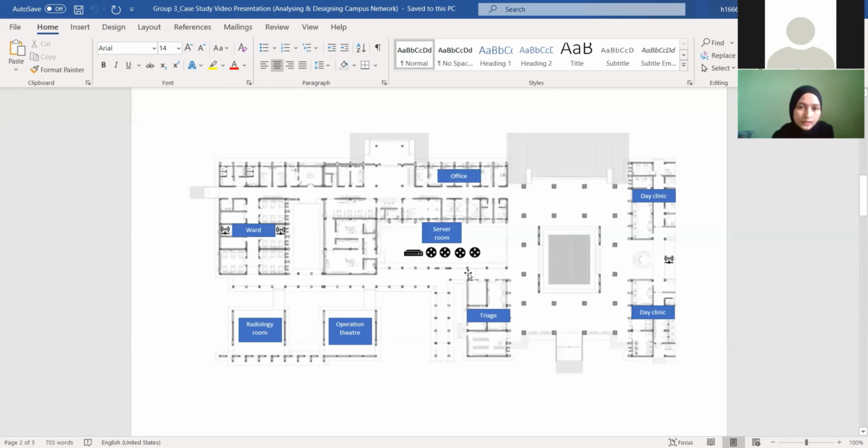Redundancy in a network helps to eliminate single points of failure to ensure better network stability and uptime in the face of events that would otherwise take the network offline. In critical applications such as safety shutdown systems, triple redundancy is commonly used.